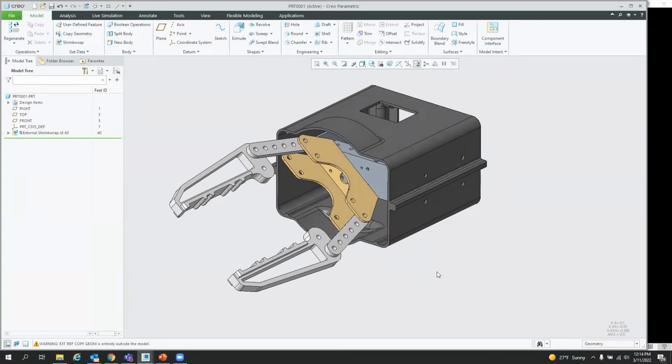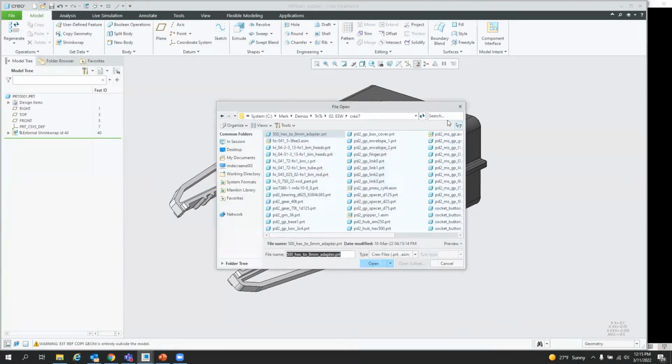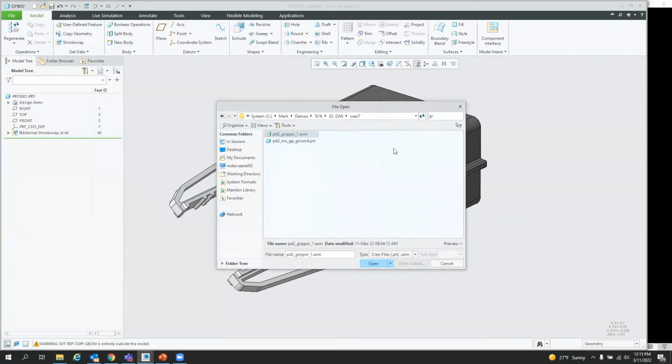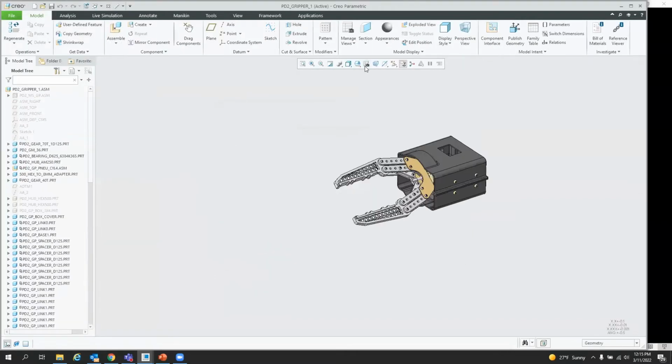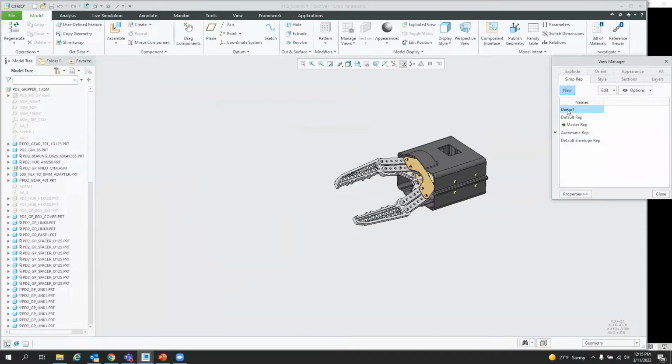And this is updatable. In other words, if I decided to go back to my master model, unless I made it independent, but I didn't in this case. So I could go back to my master model. Let's just do that real quick here. And what I'm going to do is just, let's edit the definition on that.